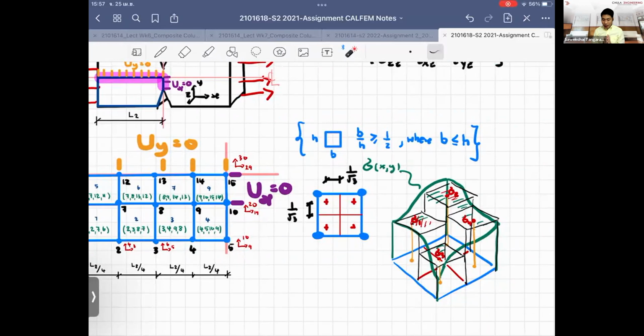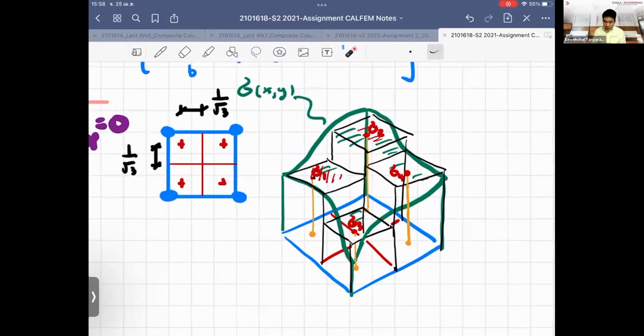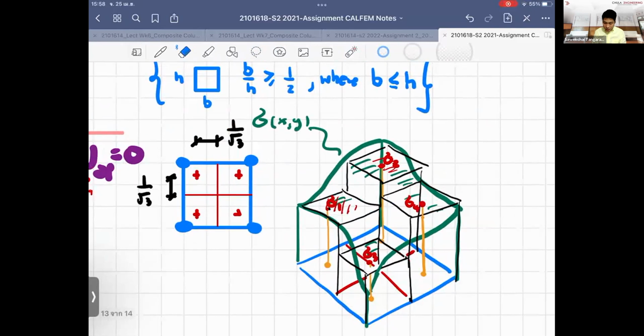So that's why in the area of finite element, people try to develop robust elements. A robust element means it doesn't need much information. You can approximate the value of the stresses, right? You see that by using the Gauss points, we just approximate them as a linear surface, but we want the nonlinear hypersurface. We use a linear surface to approximate the nonlinear hypersurface, right? Then the value of the Gauss points normally returns you a set, right?